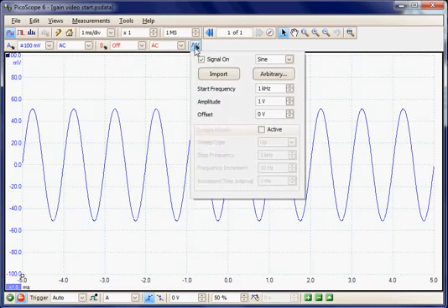It also has a generator, so we can generate very high accuracy known signals. It can generate a number of types of waveforms, but for audio tests typically sine waves are used, as this has just one frequency component and then can be used for measuring total harmonic distortion, etc. The frequency can be set and the amplitude.